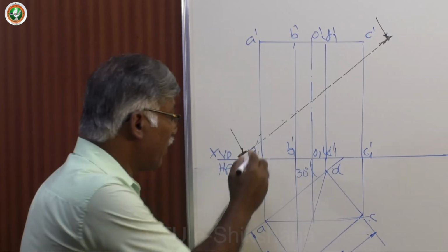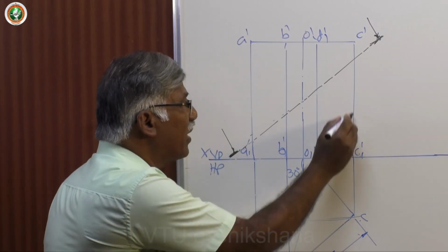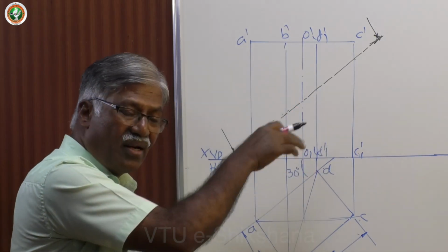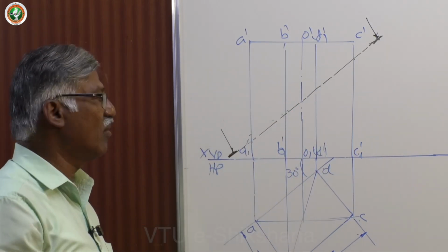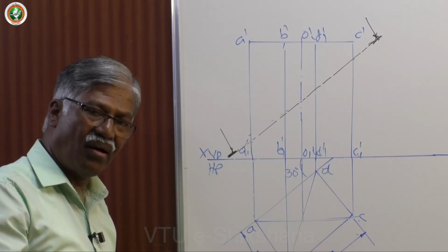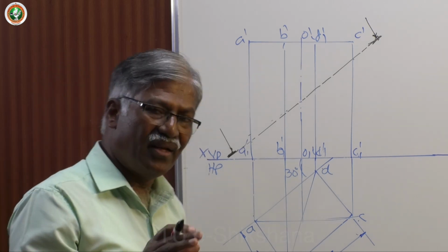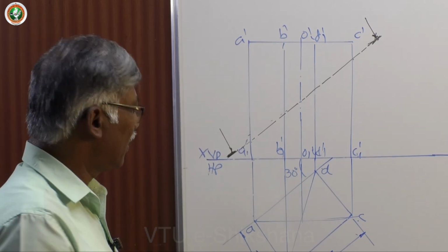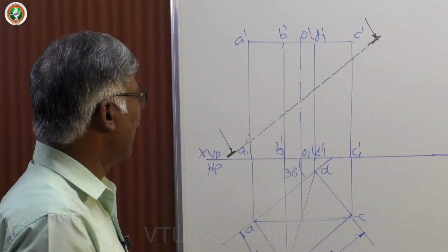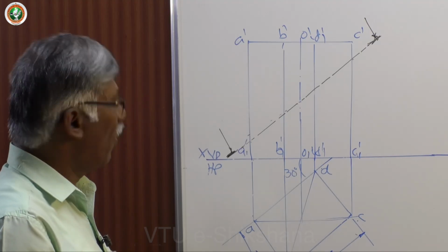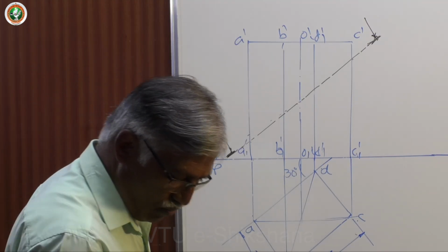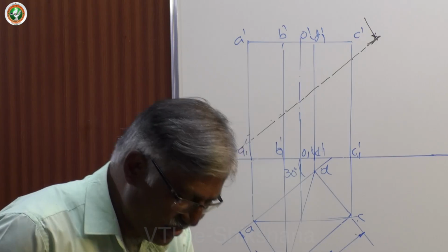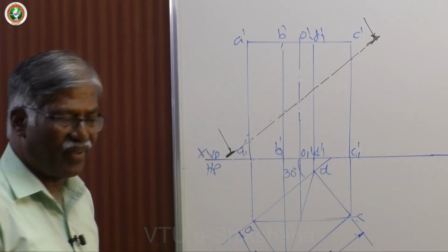That means from this point to this boundary again to this, and whatever the retained lateral edges must be in dark line, dotted line or visible line, must be in 0.5 in case of computer. Otherwise, you make it with HB pencil here. Dark line, thick line. Now, before going to dark this, identify the intersection points.